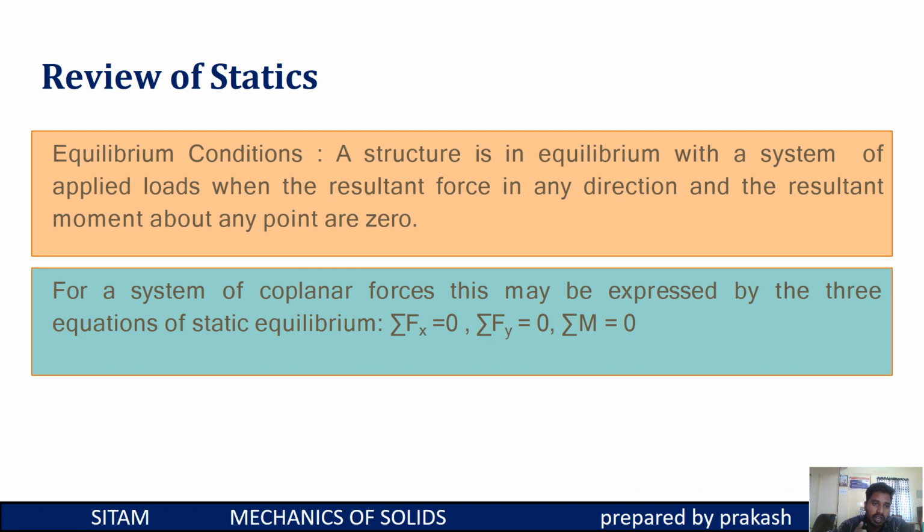Coming to statics, there are some conditions, that is, equilibrium conditions. A structure is in equilibrium with a system of applied loads when the resultant force in any direction and the resultant moment at any point are zero. That means the forces acting on the body and the counter resultant forces are also acting on that body. If the body does not exhibit any failure, the body is in equilibrium.